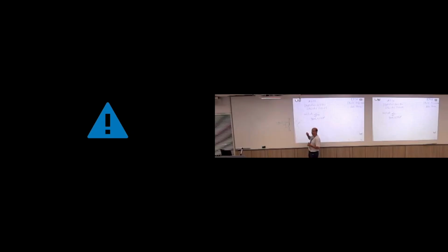Now we want to build, so one sentence more. All of our CMOS gates are inverting. What this means for an AND gate, I can state in a minute. Now we want to build a NAND gate, not AND. So what do we need? We need at the output something that is logic 1 if one of the inputs is 0, right? So we have 2 inputs and we need to connect.